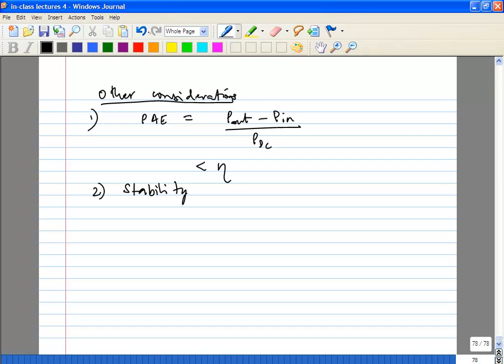So the other thing is stability. You have parasitic gate to drain capacitors, which will end up degrading the stability of the PA, and especially now that you have very large power gains, your PA is going to be very sensitive to your CGD.